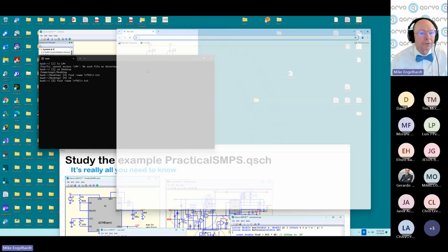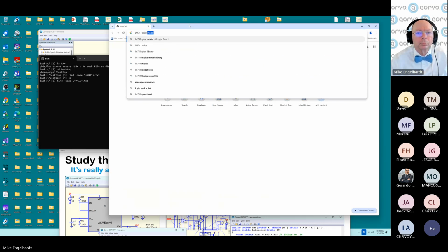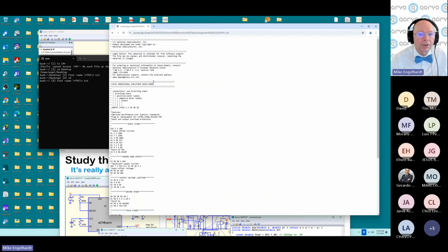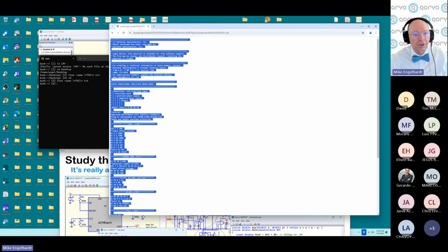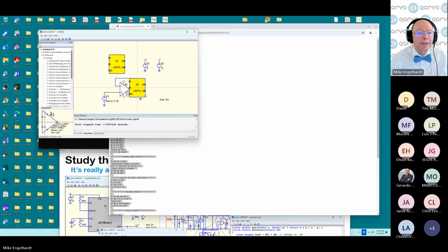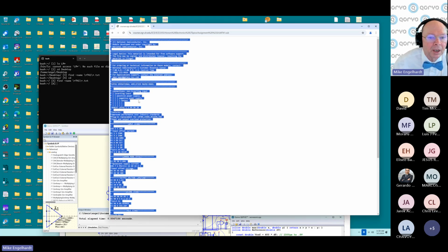Oh, let's try to get an op-amp model off the web. Okay, this looks like something. Here we are. This looks like it's the official op-amp from National, now TI. Control A, Control C, Control V. Okay, good. It's just a box. We have to figure out how to do the pins here. Fortunately, it has this section.